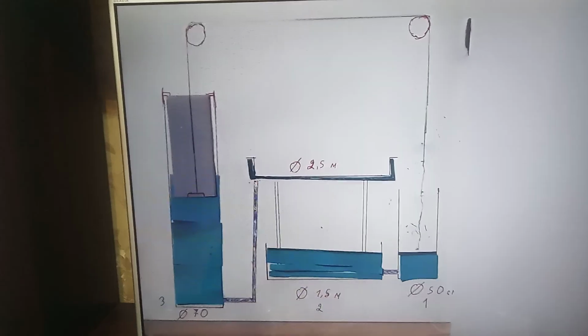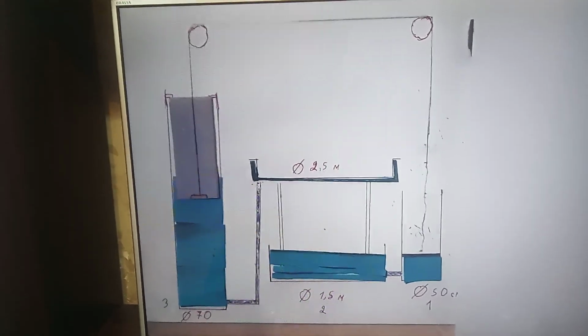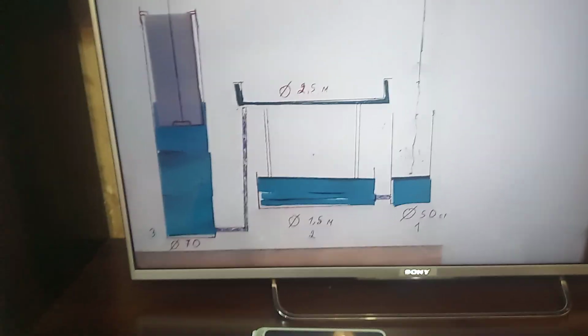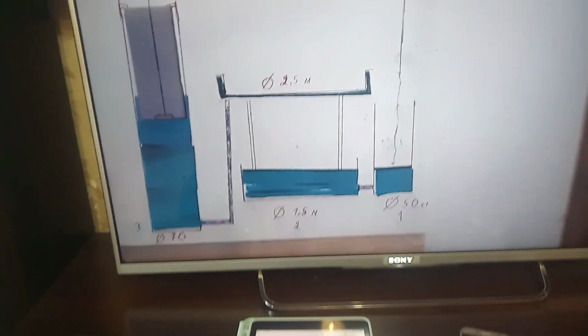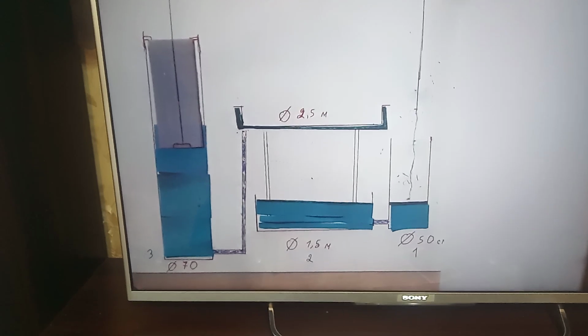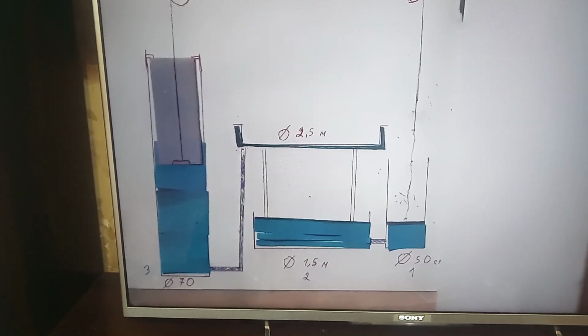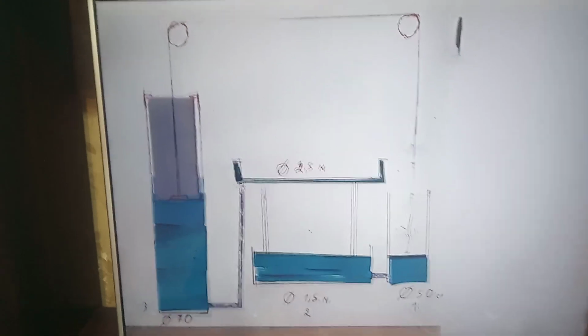the float, resting against the limiter, will stop after engaging, and the piston of the first cylinder will go down and pull the cable and open the valve, and the float will begin to sink, pulling the piston of the first cylinder up, and will begin to return it to its initial upper position.